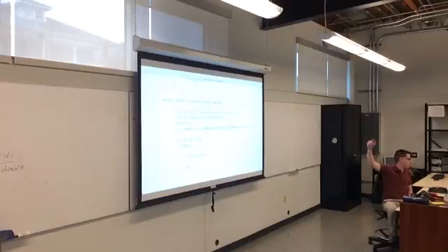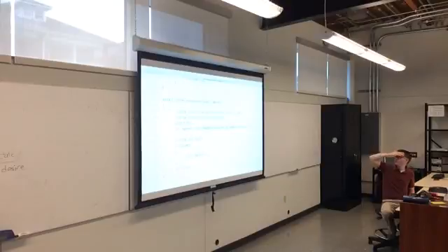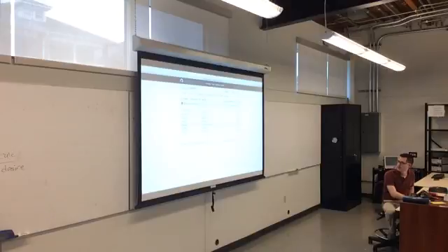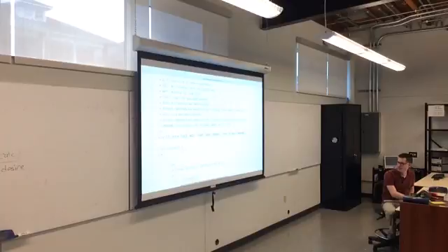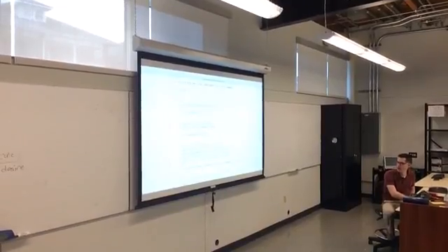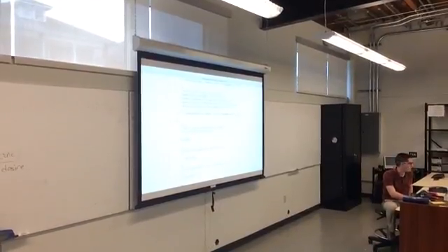Okay. This is the thing that you care about. This is your custom I2C class. Here are the enumerations of the state. This is how you get a handle to everything. You've got your write register function, your read register function. Those are what you have to implement. This is, again, implemented as a singleton, so the constructor is private. And set up clocks, set up GPIO, set up I2C. You need to implement those, same as before. Turn on the high frequency clock, turn on the GPIO clock, turn on your GPIO.